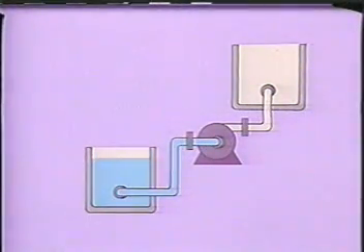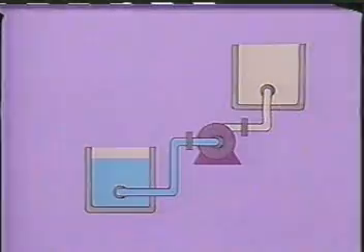If the pump is located above the suction, the liquid must be lifted, or more accurately pushed into the pump. We say it's pushed because atmospheric pressure exerts a force on the liquid.